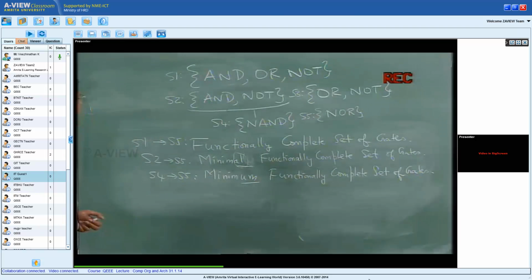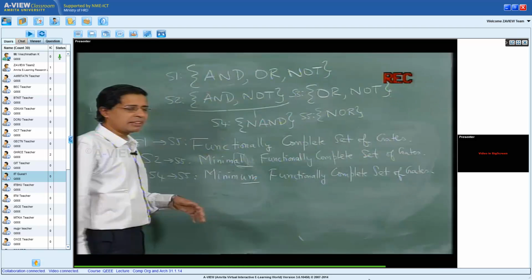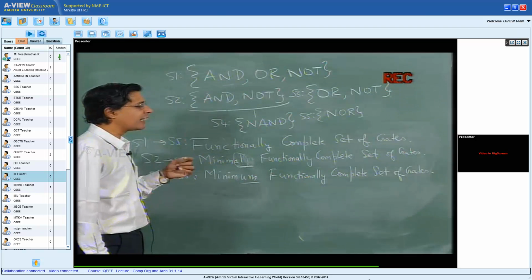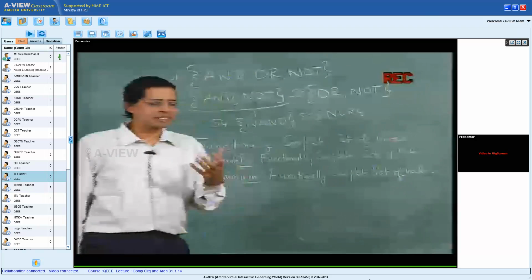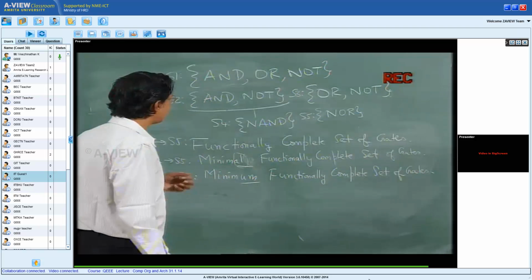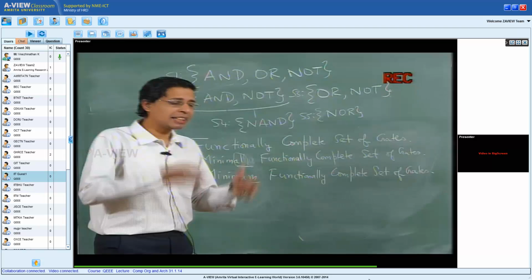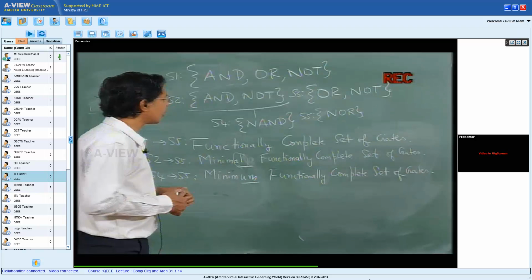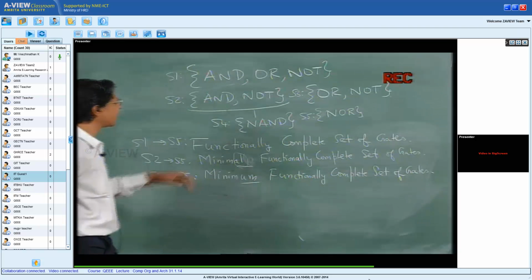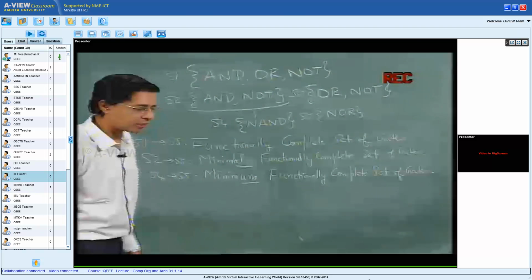Okay, so this completes our discussion. So that is why if you go and look at any fabrication unit, what they will realize is a NAND gate. They would have a circuit made for NAND gate. They have circuits made using just NAND gates, and using that circuit we can realize any larger circuit, right? So that's why fabrication units mostly concentrate on implementing, say, the NAND gate or the NOR gate, because using that we can realize any other circuit.